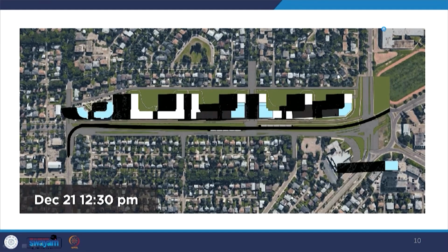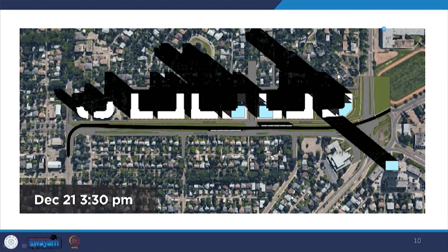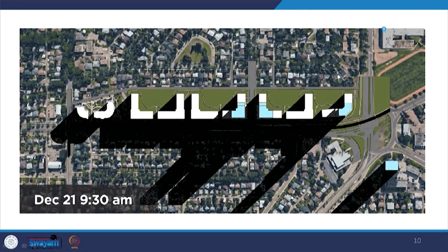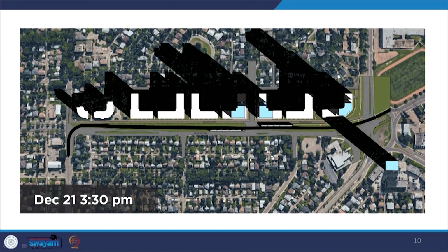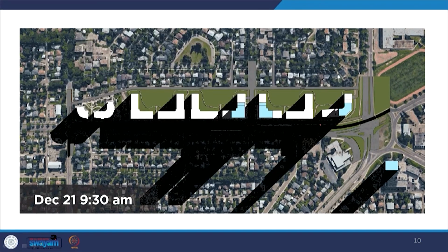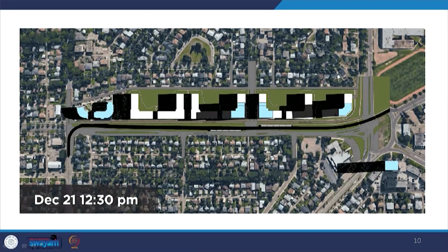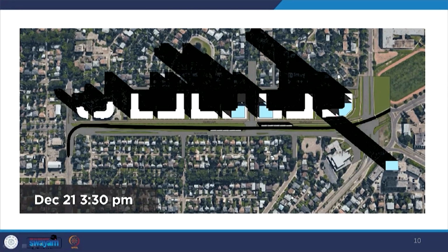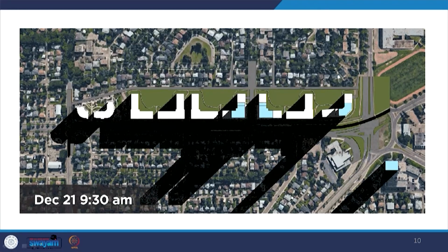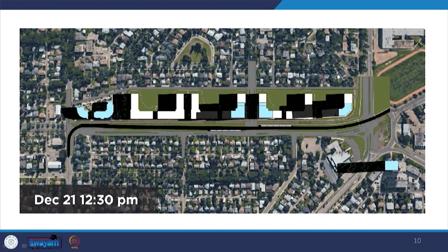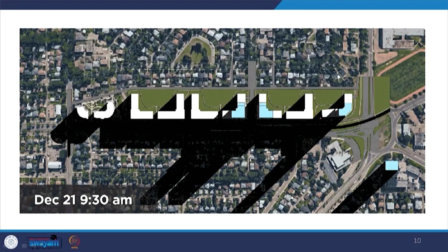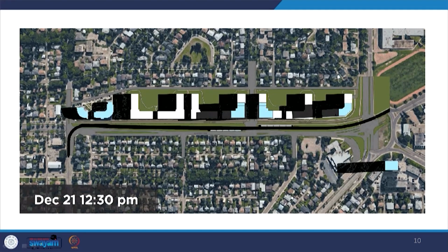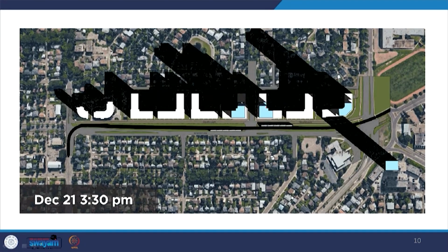If we look at this particular simulation on the screen, we have to analyze through proper simulation tools what is the shadow pattern, at different times of the day and different times of the year. So, we have to analyze the impact a particular planning arrangement would have on the buildings on site, the adjacent buildings, and also on the buildings around the site. So, alternatives of building design and placement have to be tried to improve upon the amount of insolation received, optimize it.